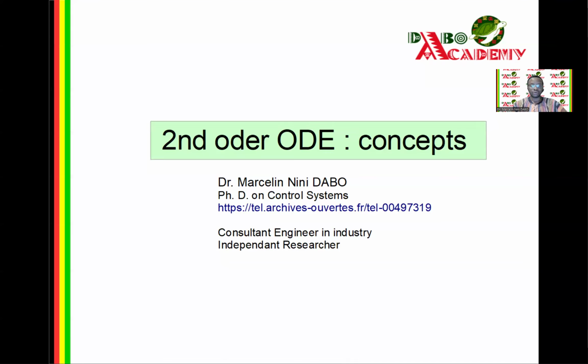In a fourth video, I have presented and shared with you a table of design of first order systems according to the performances, the temporal performances that you want to reach. If you want to reach a time response of 95% at a fixed value, like 1 second, you can derive the time constant related to that. The formula is known.